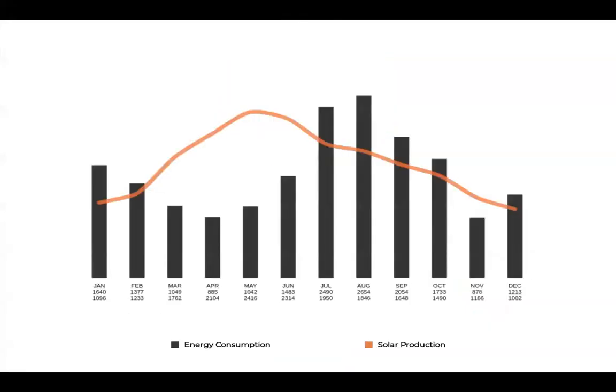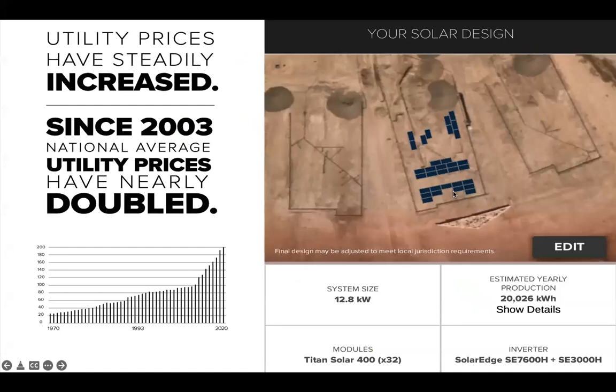And we use all those factors. So if we take a look at this one right here, we have a mixed azimuth. So it looks like 175 degrees south, right? Maybe 170 on the azimuth. And we're looking at probably 80 and 260. So we have a mixed array.